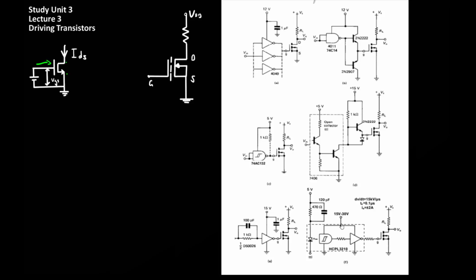The advantage of this configuration is that very fast rise and fall times can be achieved by having the appropriate drive circuit, and this circuit will be controlled optically from control circuitry. In this way, the control circuitry is not responsible for providing the sink or source current required to quickly switch this power MOSFET on and off. Furthermore, this optical interface means that level shifters such as the one used here are not required to drive the gate.